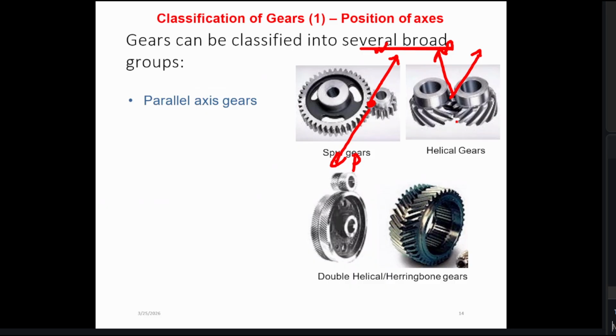So that is why the helical gears are mainly used for quiet operations where we need low noise generation. As you know, in the automotive gearboxes, in common gearboxes, helical gears are used to reduce that noise. But in reverse gear, the idle gear is made of spur gear, which generates a bit of noise.